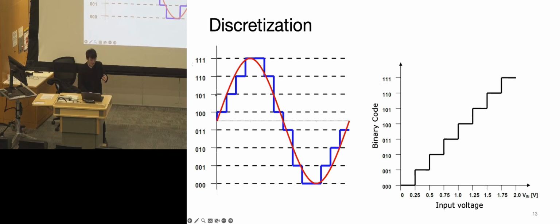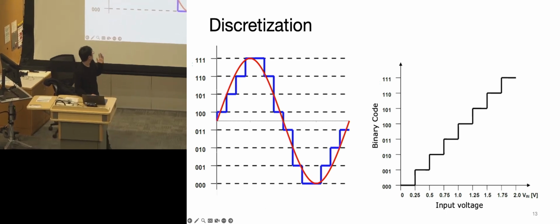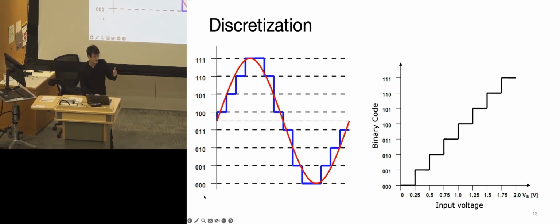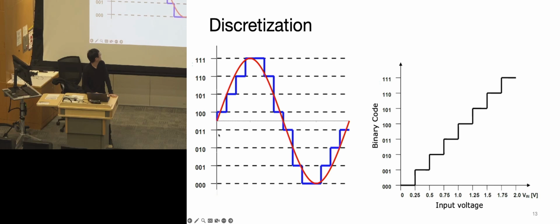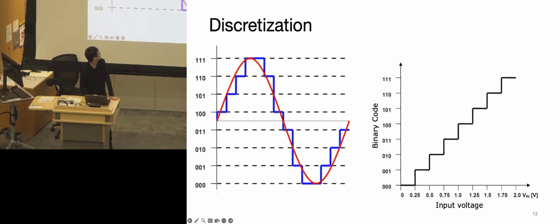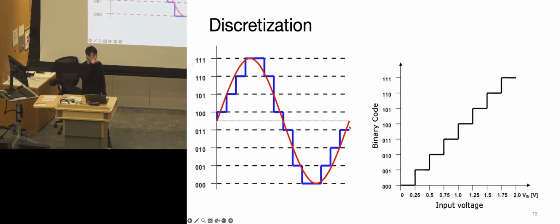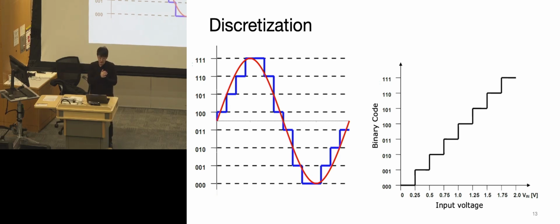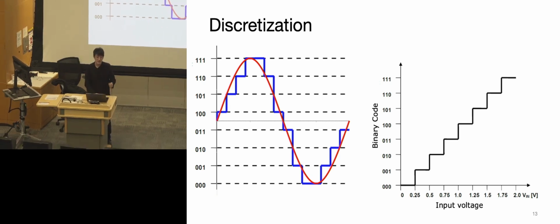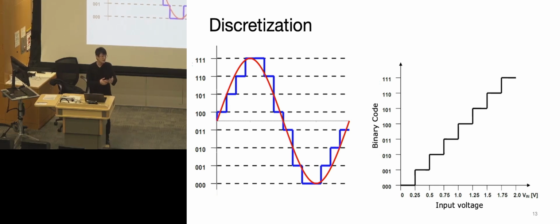If we have a perfect sine wave here and only use 3 bits to sample the value, then we have these little steps of values across the entire signal. Because we use 3 bits, there are roughly 7 steps peak to peak, and this resolution can change based on how many bits you assign to the ADC device or chip.